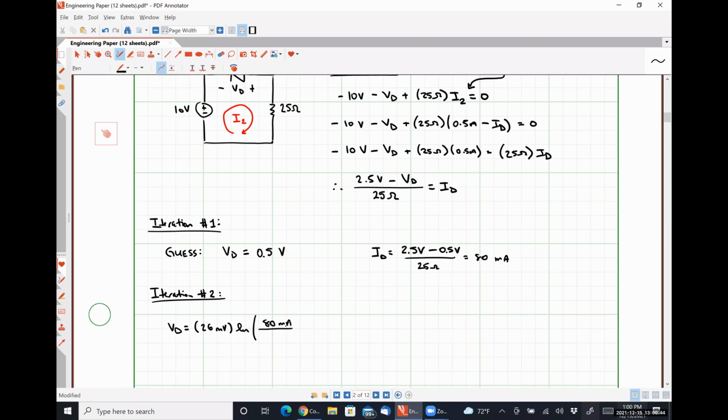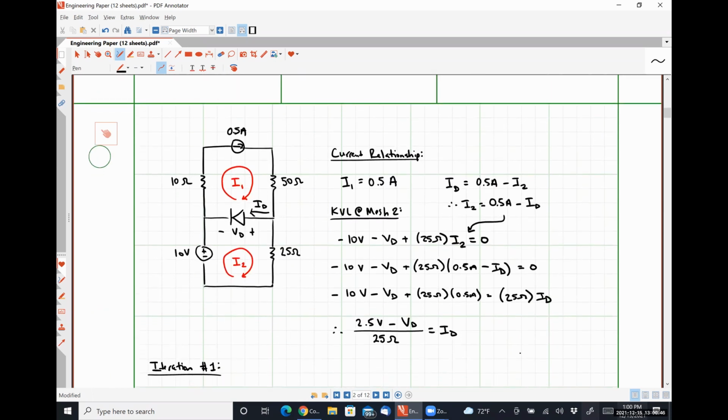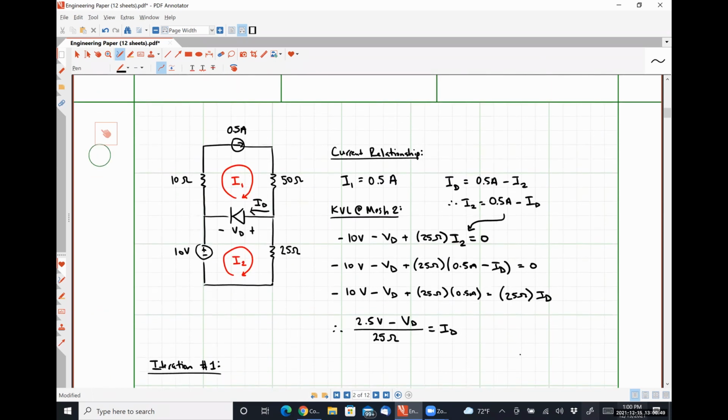divided by, okay, so this is something that's pretty important here. I forgot to mention to you guys what the value of I sub S is, which is critically important to doing this iterative method, so I apologize. In this particular example, we're going to say that IS, our saturation current density, is 5 nanoamps. Also, we're going to explicitly state to use the thermal voltage value of 26 millivolts. That's usually going to be what happens, but it's nice to be told what to do. So I apologize for forgetting to include that portion.